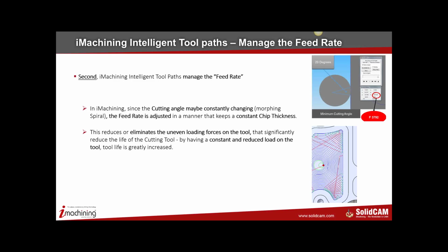Why am I telling you this? It's important that when you're cutting super alloys, your tool load has to be as near constant as possible. Because if you vary your tool load, if there's a variation, which means that your mechanical and thermal stresses are increasing, or they are changing very rapidly, and this can be really bad for the tool. Your tool can start chipping, and once it starts chipping, it doesn't take much time to disintegrate on such materials.